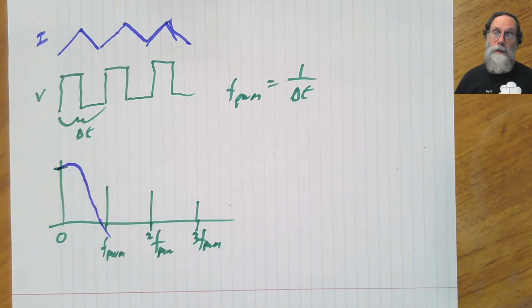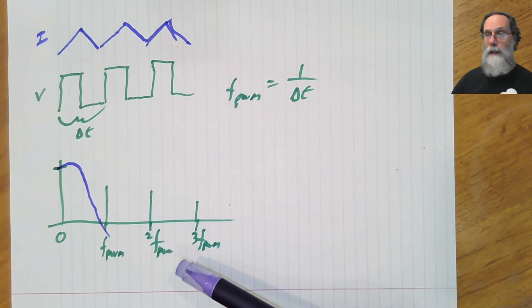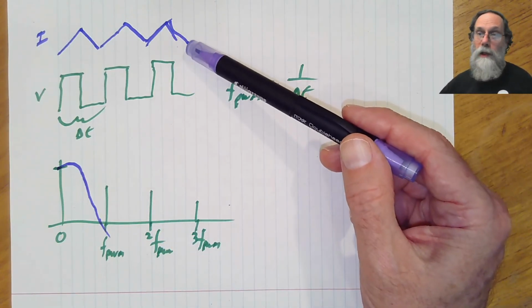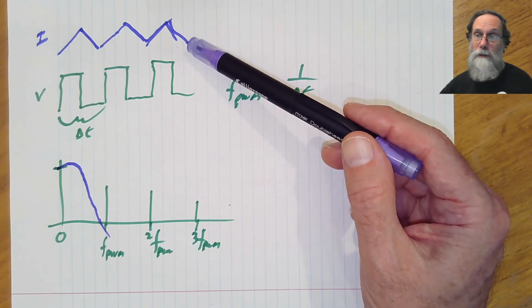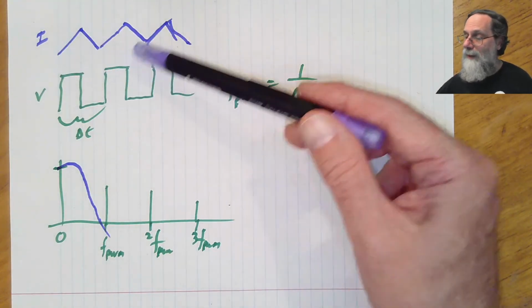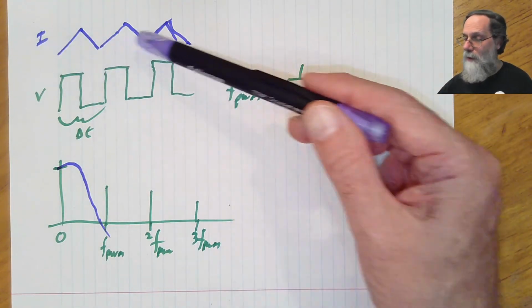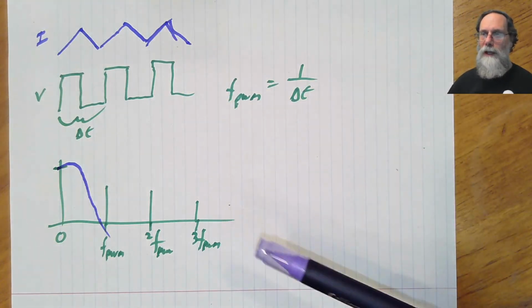And what we will be doing when we use PWM for our Class D amplifier is to use both of these techniques. The thing that we're driving in the Class D amplifier is a loudspeaker, which is basically an inductive load. And so we'll be getting a lot of averaging here from just using the current rather than the voltage is what's really driving the loudspeaker.